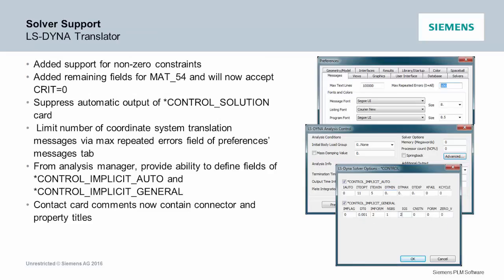We've added some Dyna stuff. Again, this is kind of launch control and setting up the jobs and getting them running, and then we continue to add material property support. We've also added a user-defined material for Dyna where you can set up any Dyna material. You just tell it what the keywords are and what values you want. So now you can actually handle any Dyna material. You can kind of code it up yourself.